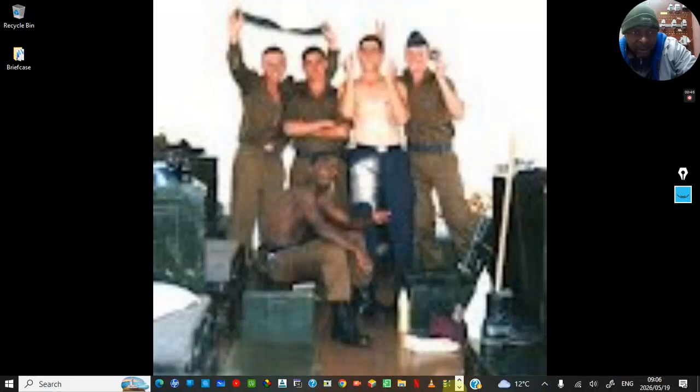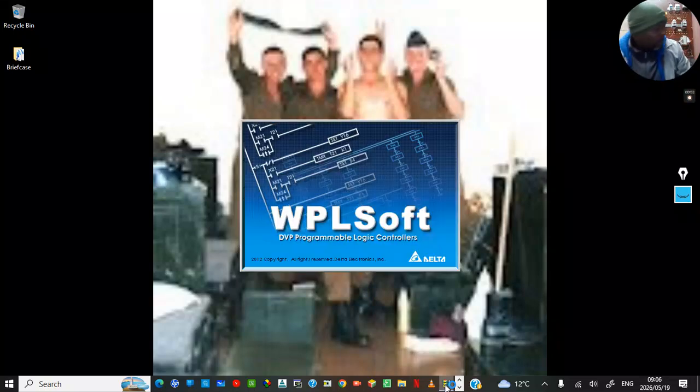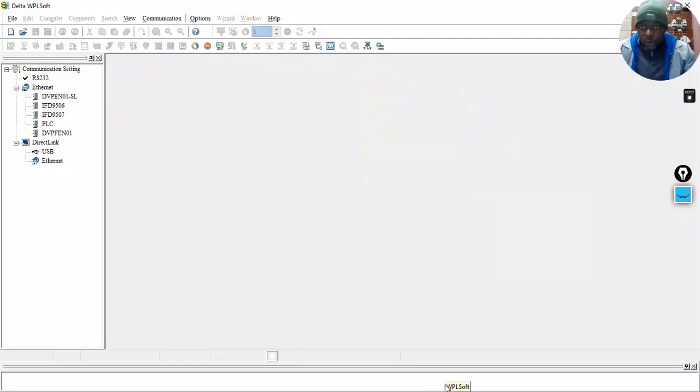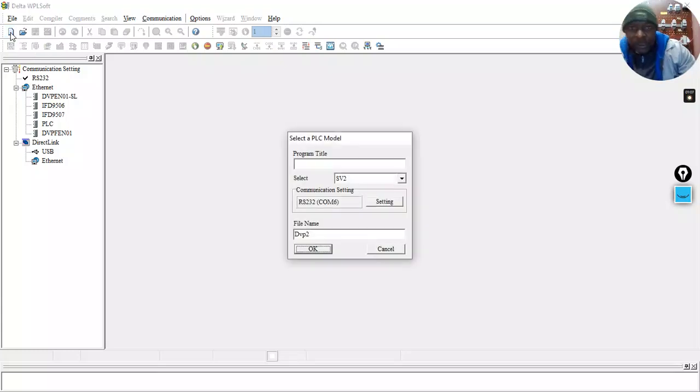Let's go and get our software, which is the WPLSoft for the Delta PLC. Where we have our PLC is the DVP-PS02, and there is our programming platform. Then we say new, we can hit Control and N. It will give us that dialog box, where we can say what our new program title is going to be.